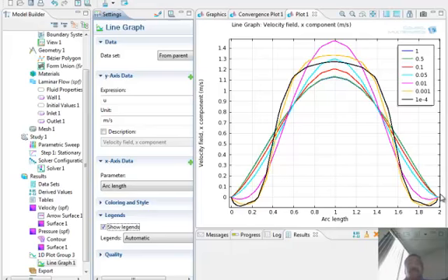Okay, that's because of the reverse flow that you get. And of course, whereas in the low Reynolds number like 0.5 and 0.1, you don't have the reverse flow. You have almost a parabolic profile. Okay, but here in the center, the profile is not parabolic. It's almost like a flat jet, because by the time it comes out, the velocity is almost flat in the middle. Okay, so the velocity profile changes quite a bit as you change the Reynolds number, and it plots for you all the different viscosities.